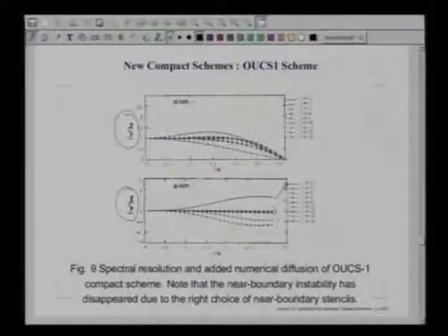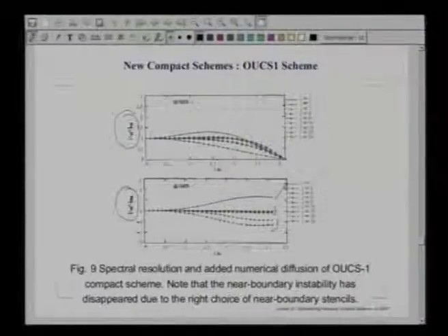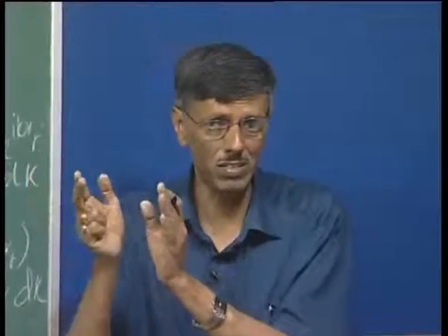The large values that you are getting are near the outflow boundary, and at the outflow boundary what do you want? Most of the time in computing you are getting the propagation of disturbances, and if you do not set the outflow boundary condition properly, they actually reflect from the outflow boundary and distort the solution. So, we want to avoid that.